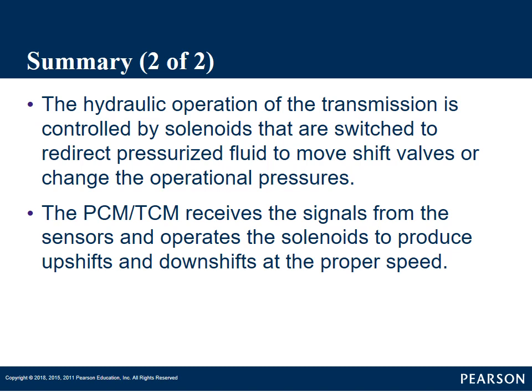So just remember that the biggest thing I want you to get from this electronics class is to know that these electronic transmissions are still shifted hydraulically using hydraulic pressure. We're just using solenoids and sensors to control that pressure more accurately to shift our transmission.